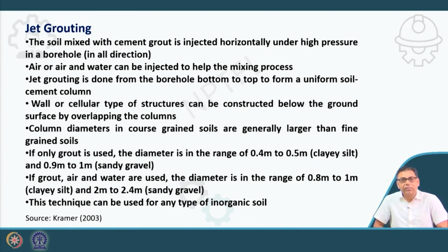Now in jet grouting, the next one, the soil mixed with cement grout is injected horizontally under high pressure in a borehole. So here, under high pressure, the soil mixed with cement grout is being injected horizontally in a borehole in all directions. That means first a borehole is constructed, then within the borehole at different depths, the cement grout is injected horizontally. That means it goes in the lateral direction, any direction or all directions, horizontally.